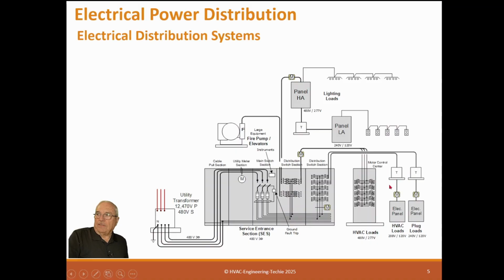But then you would have a little problem here, because you've got a meter on this panel and a meter on this panel, because this is a plug load and electrical load. The whole idea is you want to have segregated panels that only have one load within the panel. And then you can meter that, so you can isolate the HVAC load. That's the only one the operators can actually affect. Lighting control, they could change the schedule and affect it a little, but plug load, they can't change at all. So the only thing they can actually affect is HVAC, so we need to try to meter HVAC separately.